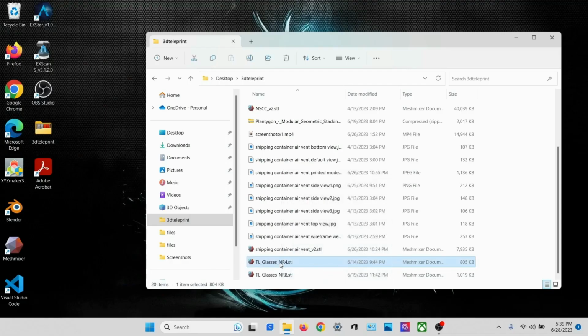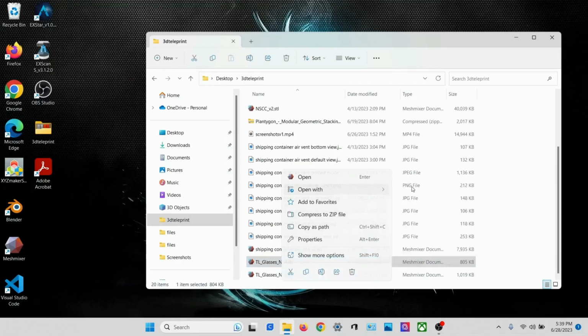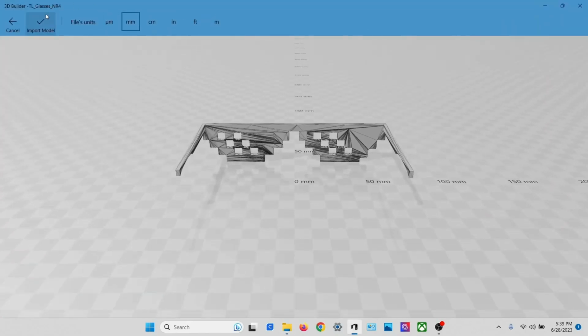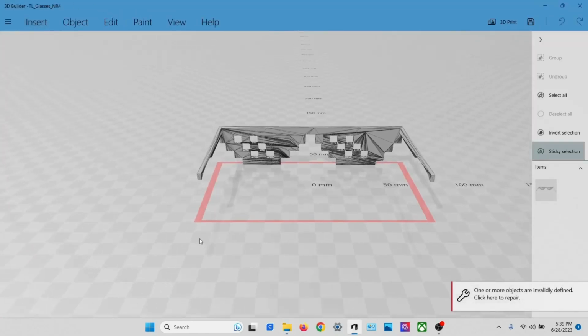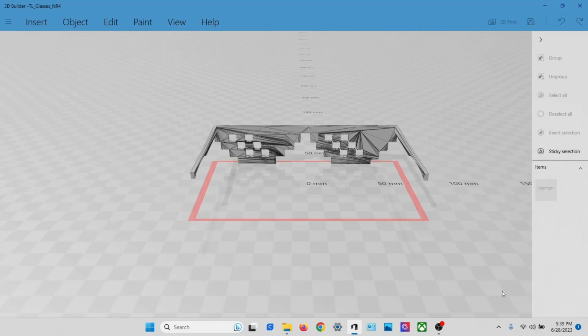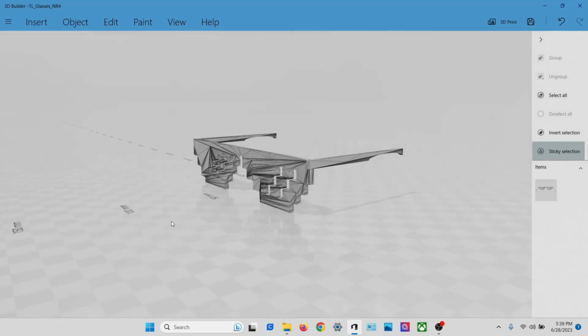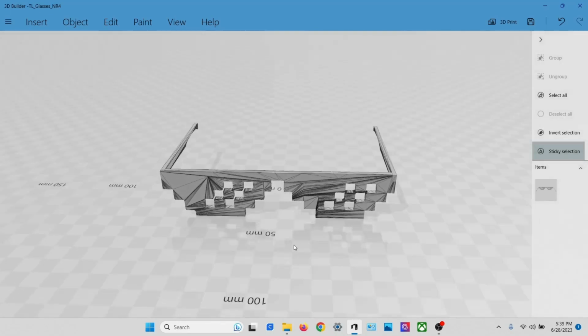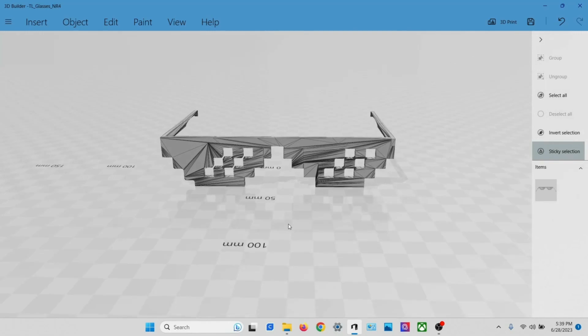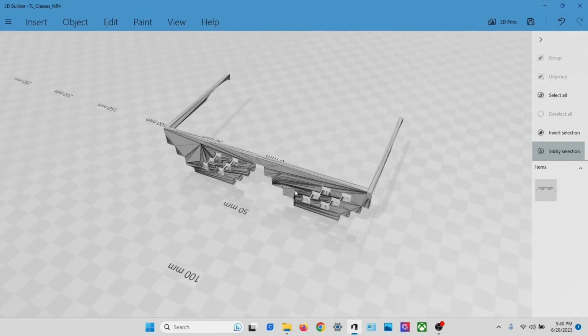Right-click your file and select Open with 3D Builder. Select the checkmark. 3D Builder does a check to make sure the STL is manifold. If it has issues, click in the bottom right corner to authorize the repair. If this repair breaks, your part will need to be redesigned to be uploaded to 3DTeleprint. To learn how to remesh your object using Meshmixer, a link will be provided at the end of the video. Step 1 is done.